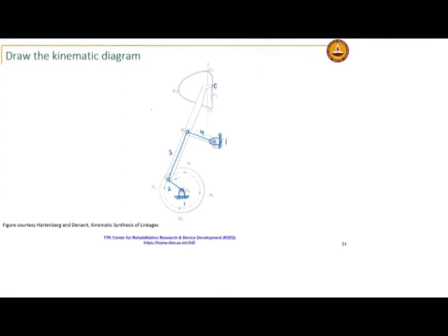and so it will advance the film strip in that fashion. Okay. So, since this is a point of interest, typically in the kinematic diagram you would also show the point of interest, but to indicate that it is not a link, again you will show that it is part of link 3, you will show it in that fashion. And you also do not put an open circle there, because that would indicate a node for a revolute joint. So, this is the proper way to draw a kinematic diagram. So, you draw the revolute joints.